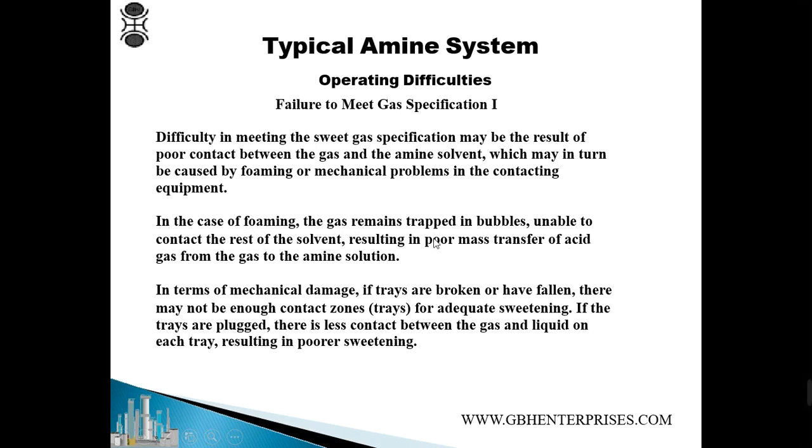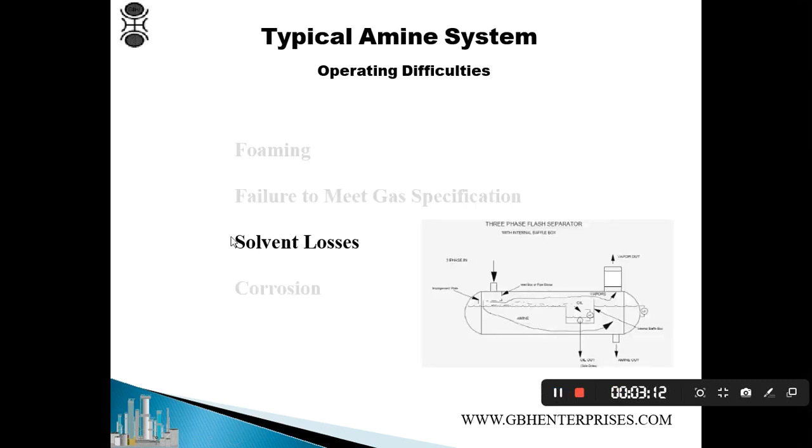Because the bubbles are trapped, no chemical reaction occurs, so no H2S and CO2 is removed. Sometimes the trays are broken, a mechanical issue.